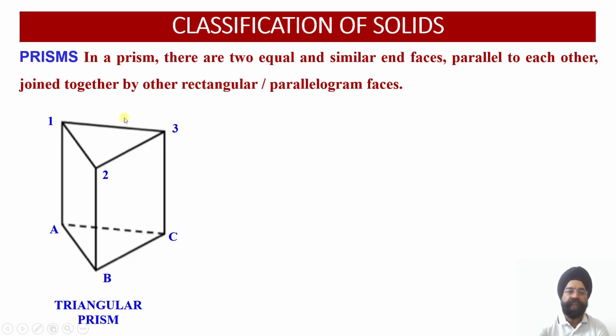So for any solid, all points of the upper surface as well as the lower surface will have to be joined, and all the vertical edges again have to be joined. Now the question remains: the edges or the faces which we are able to see from the front side or the top side will be drawn using the object line or the darker line. The edges or the surfaces which we are not able to see from the front side, which are overshadowed or overpowered by the front faces, will be drawn with the help of hidden lines. That is, these edges have become hidden over there.